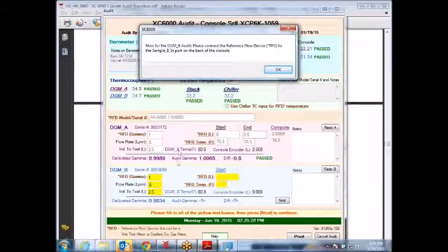The terminology comes a lot from the older mechanical meters that had the dials like your gas meters at home, and you get a little mechanical slippage and different things like that. What can happen is they read over a certain volume, they'll be a little bit off from a standard or a reference. So what you do is you apply a factor to get it up to what that standard would be. So that's what it's doing.